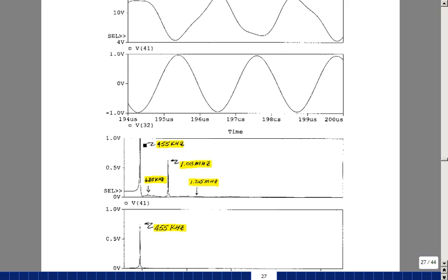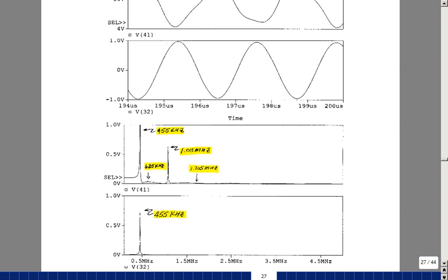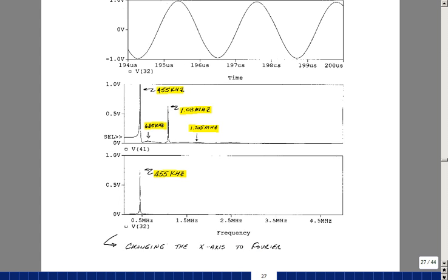Now that's coming from the fact that we're going to multiply GM times VPi. VPi has a 624 kilohertz signal, and that's going to multiply the 1.08 megahertz variation of GM. That's going to create our multiplying circuit. It's going to create two frequencies, 1.705 megahertz and 455 kilohertz. But the tuned circuit, which is transformer T6, and again this is the output of T6, is only going to let through the 455 kilohertz signal. And so that's what we're going to hear in our radio.